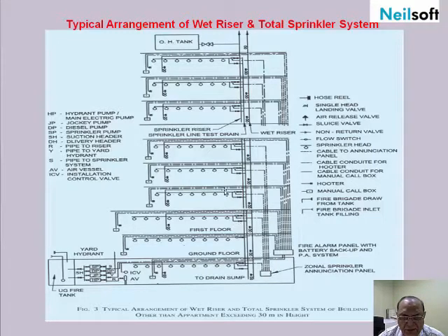These are the zone control valve, as we have seen in the details. These are required to monitor the areas where the sprinkler system is in operation, and the signals are taken from the flow switches, which are part of the zone control valves. However, some things which I have explained over here may not be properly understood.